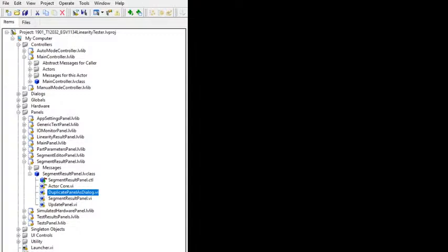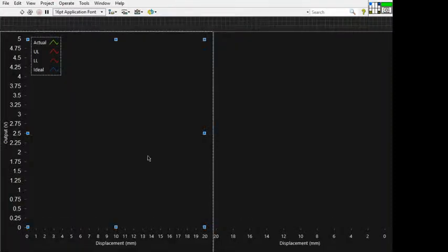So what I ended up doing is, if the operator clicks on a graph, I did a double click event, so I had to create a double click event myself, right? If the operator clicks twice within a certain amount of time, then I'm going to spawn up a dialog of this exact actor. So it's a pretty easy implementation to do. Let me take a look at it real quick. Let's open up that VI.